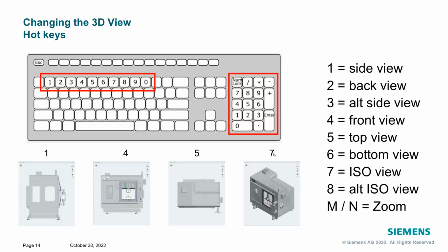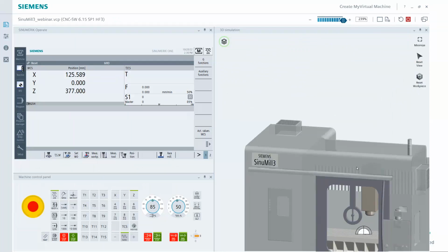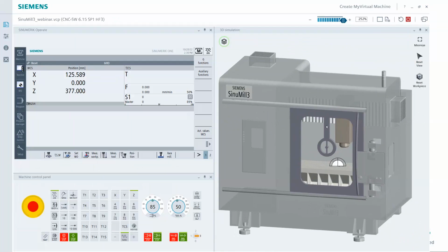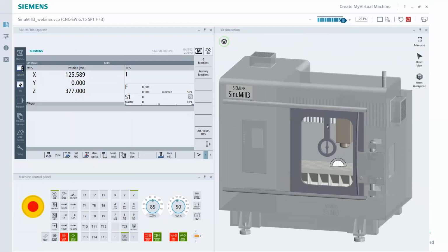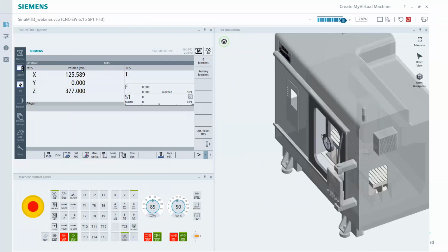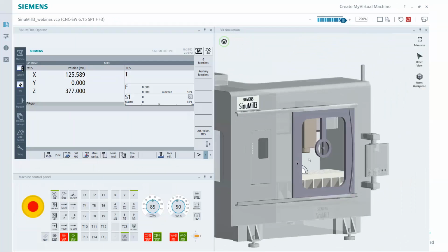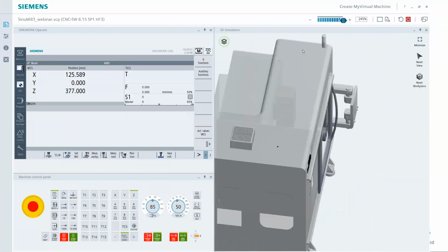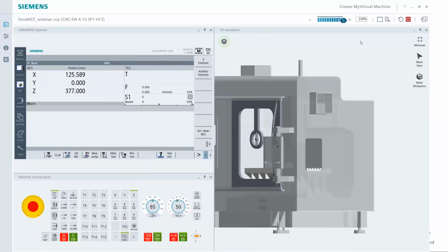So to try that here, again, my left button is being held down and I can pan around. I let go of the left mouse button, and I can zoom in or out with my wheel. I hold my right mouse button down and now I am rotating. And as it rotates, you see you get a little black dot. That's the point about which we're rotating. So at the time when I put my mouse down, I can control the point of rotation.